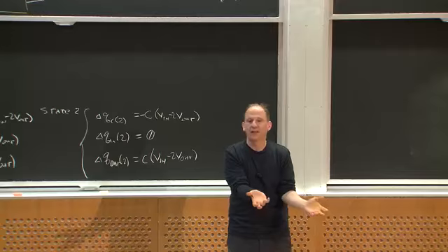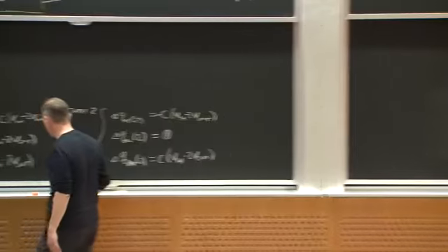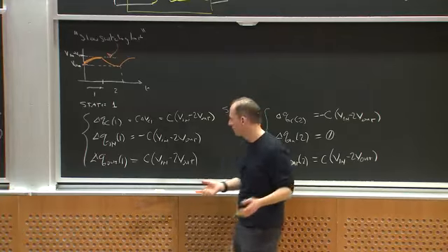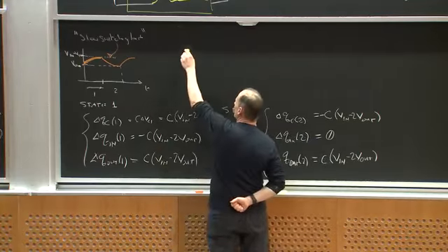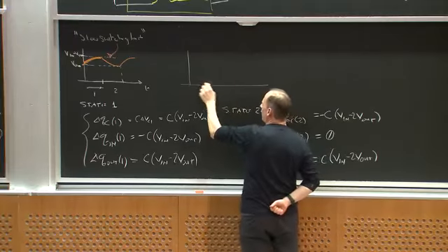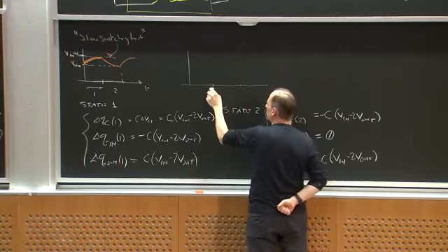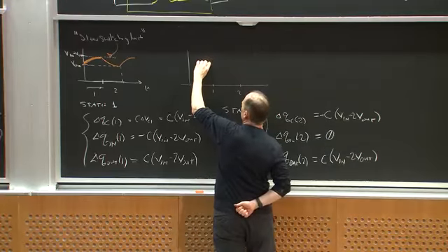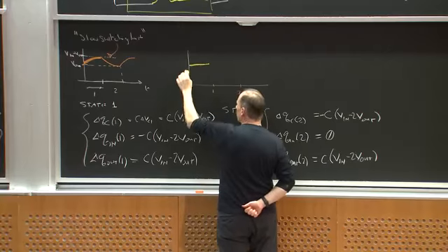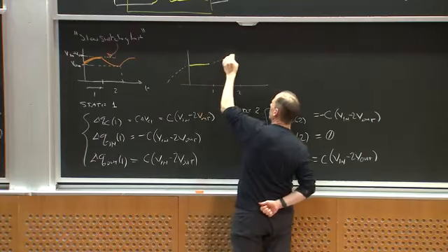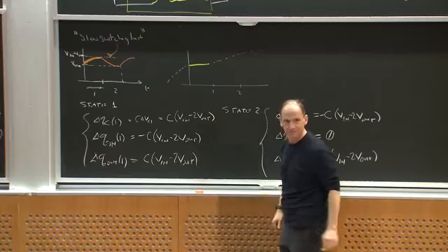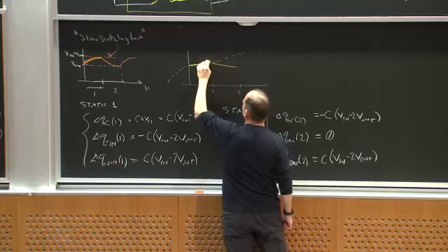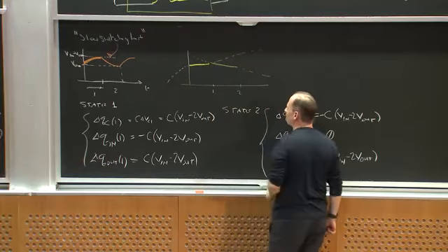The extreme limit of that is the capacitor sitting close to some voltage, and it only charges up and down a little, right? So, suppose I made my time scale really short, and here's state 1 and here's state 2, right? In state 1, it just charges a tiny bit, which is part of a much bigger RC charge. And then in state 2, it discharges just a tiny bit, which is part of a much longer RC time charge, right?